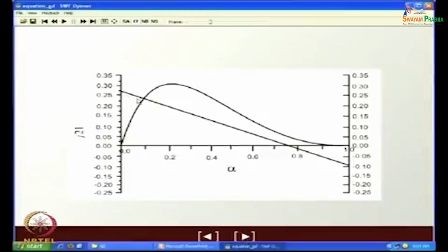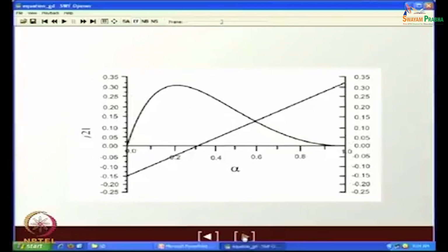We have found out that for co-current upflow, co-current downflow, there is one particular point of intersection. Under all circumstances, this point shifts to higher alpha when we increase J2 and we decrease J1 as expected, and the opposite behavior occurs if we decrease J2 and increase J1.